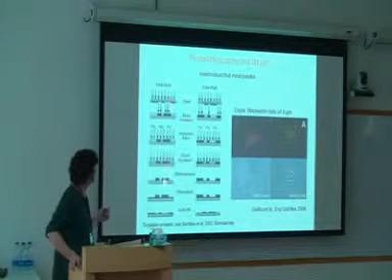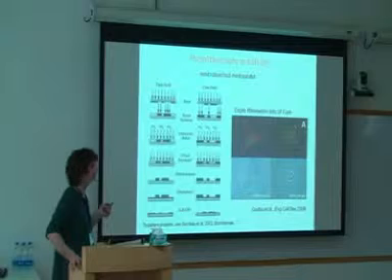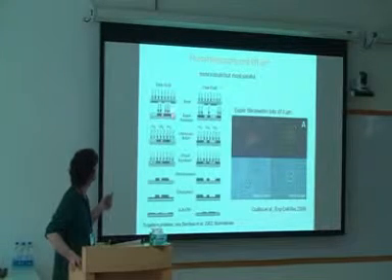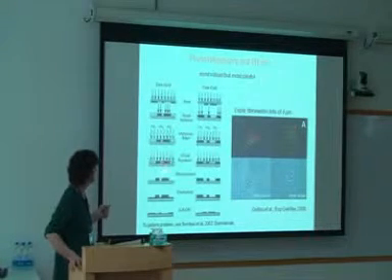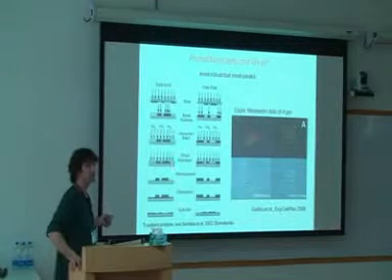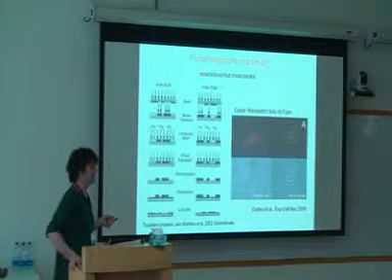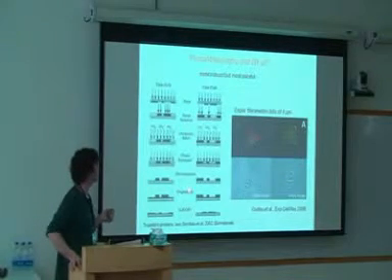The problem is, as you see, you have a large number of steps, and this usually has to be done in a clean room. You need a spin coater to put your resist. You need all kinds of solvents to remove it. And for each cover slip, it will be quite painful to go through all that. But in case nothing else works, this will always work, I think.